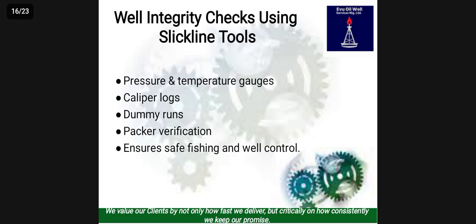Well integrity checks using slickline tools. Use tools for well integrity, which includes but is not limited to the following: pressure, temperature logging, caliper runs, dummy runs, packer checks, to keep you from fishing blindly in a risk well.